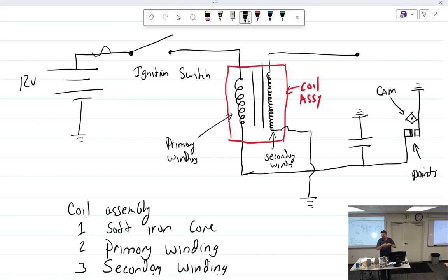Or you guys ever do this with any sort of automobile? Just did that yesterday. Okay, and what'd you do it on? A car. So you just take the plug out, plug it in, and lay it down on something metal, so you have a complete ground. Don't hold it. Make sure atomized gas is coming out. You lay it down, you crank it, and it's hard to see, right? Well, in my case, that's why I was testing, because it doesn't work. I have no spark, but it should. But it's kind of hard to see.